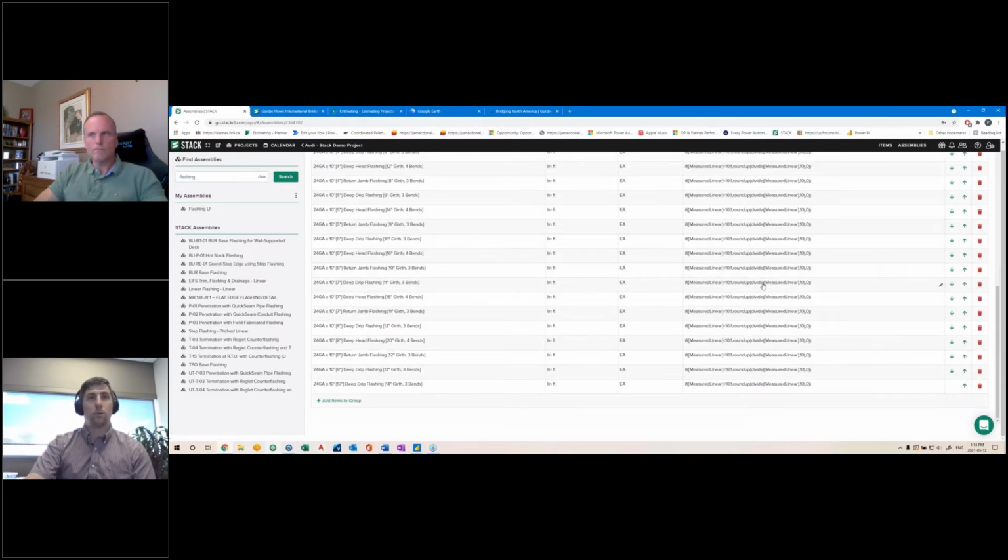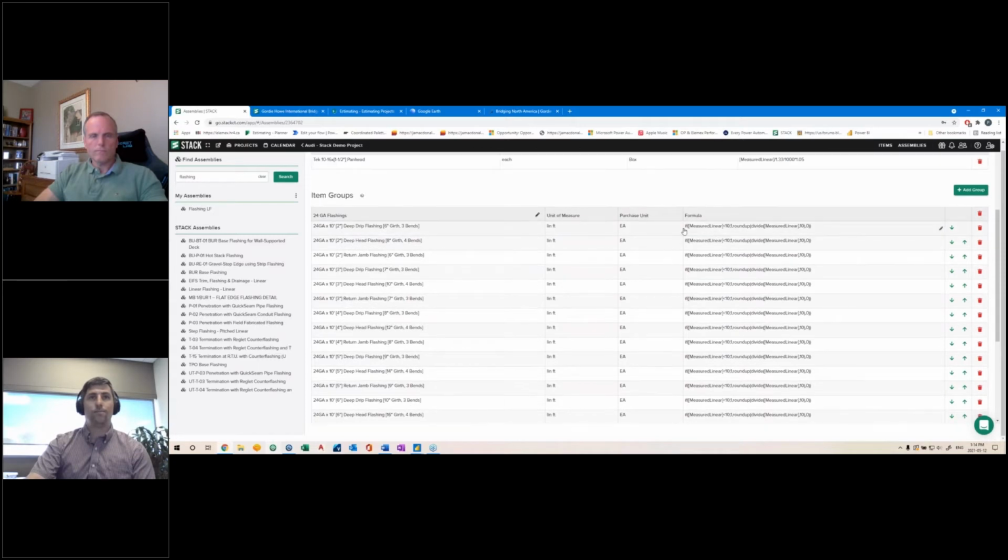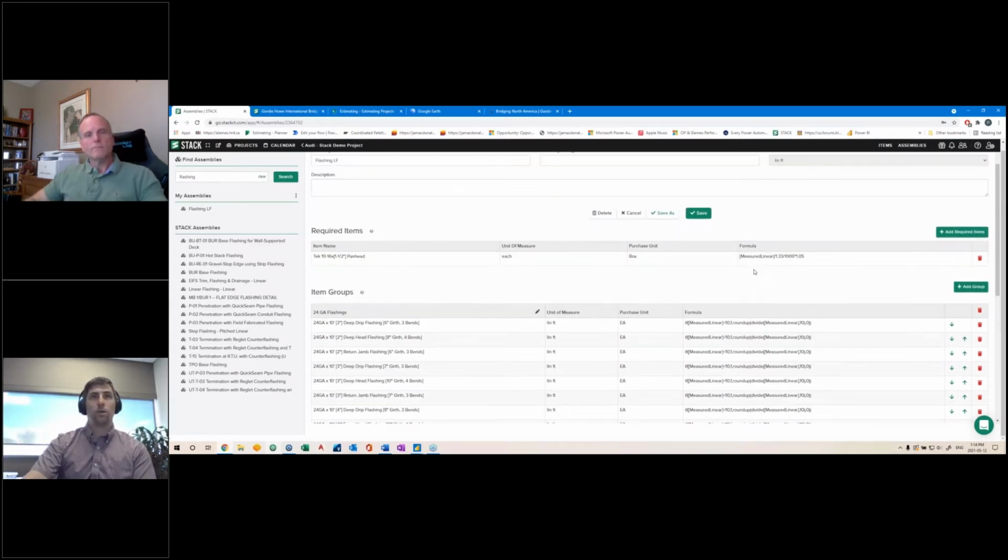And I've really been exploring how to use these conditional formulas throughout. Another great example would be, if the quantity is over a certain amount, we want to run a different productivity. Or let's say the height is over a certain amount. With our drywall company, we know that there's a labor rate up to 10 feet, and then there's a labor rate above 10 feet. Because above that 10 feet, they're going to need different access equipment. There's going to be more up and down. You might have 2 guys handling the board. So we can take those measurements into consideration. We could say, if the height is more than 10 feet, then carry this productivity rate, but if it's under 10 feet, then carry this one.